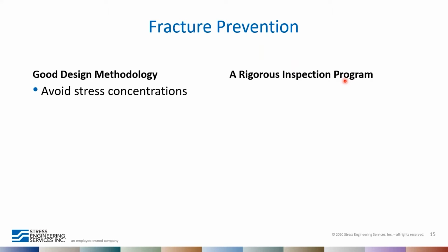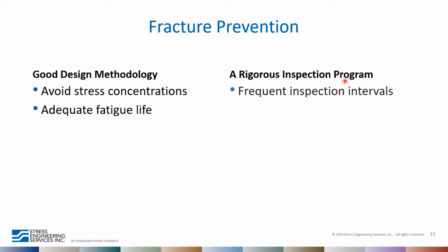But again, a good design methodology will address things like stress concentrations and avoid them, especially in a service that is known to have maybe fatigue and various other things like that. A good design methodology will also adequately account for all the loading that the component might see in order to ensure that it has adequate fatigue life. A rigorous inspection program will set the right intervals, will inspect at frequent intervals, and the goal of that is really to identify subcritical cracks before they become a problem so that you can prevent fracture.